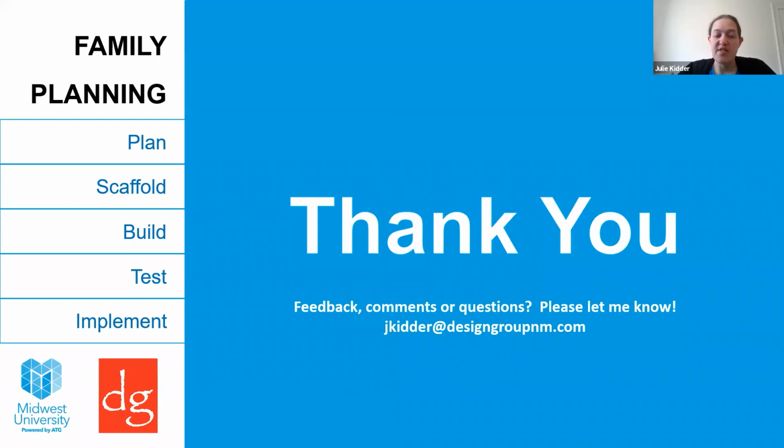I had parameters that I thought I could do as family parameters, and I went back and changed them to shared parameters when I determined I needed to do something more with them. It's also important that if you're trying to use those values in a schedule, they also have to be shared parameters. While there are some that I'm not going to display in a tag, I needed to be able to filter schedules on that information.